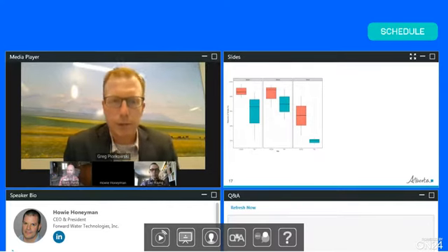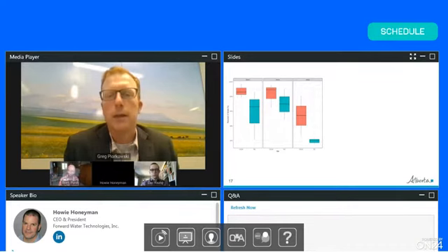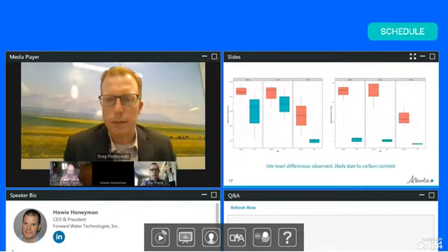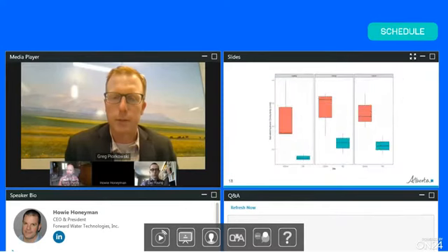I also wanted to show there is a difference between the sites. In our CDC North, which is in the pinkish color here, we did observe a higher percentage removal than our southern site. We're largely attributing that to dissolved carbon, primarily within the source water itself. So the more we supplement the system with carbon, the greater removal that we get. There is a noticeable trend, more obvious at the northern site, that the barley and the hemp do emit more carbon, so the concentrations are higher than the equivalent for wood. That could be one of the driving factors for the better performance within the residues.